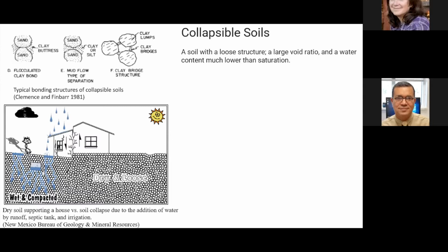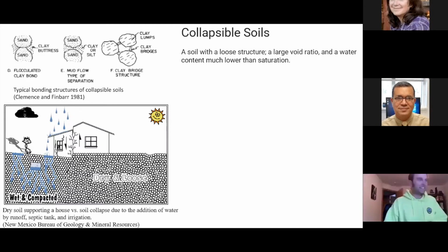In this case, this soil automatically under its own weight is going to fail its own structure and then compact, and is going to suffer a huge amount of settlement. This is the source of the problem. The huge amount of settlement or the considerable amount of volume reduction in the soil is going to lead or cause damage to our structures.